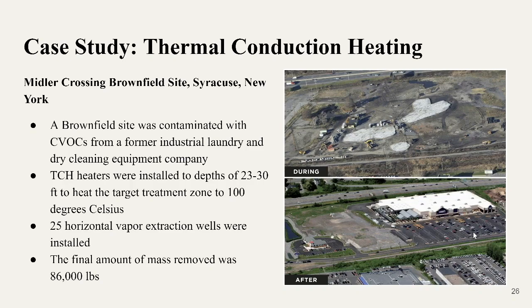Challenges encountered were moderate to high groundwater velocities within the fill, and underlying rock and soil required installation of a sheet pile cutoff wall. The performance of the remediation was documented by samples from 51 locations. At the end of the project, all areas met the cleanup standards after thermal treatment. Currently, the site is redeveloped in the location of a large home improvement store and a federal credit union.